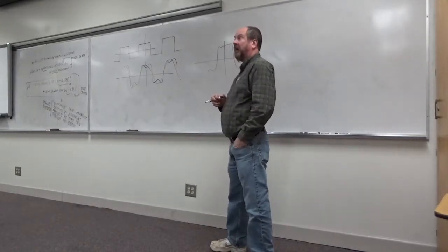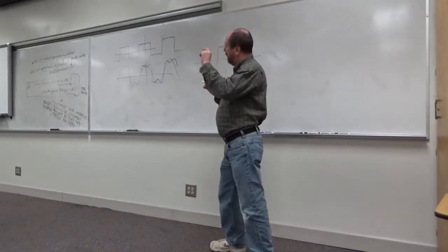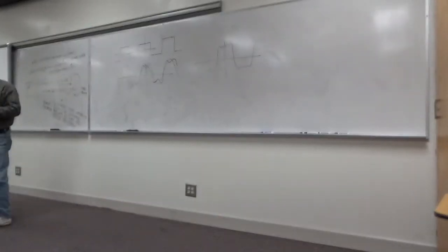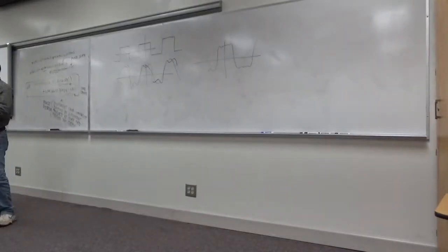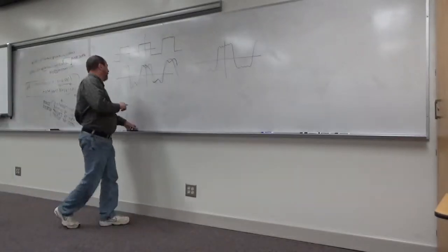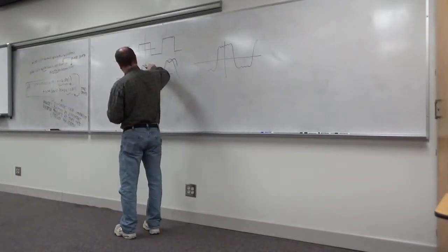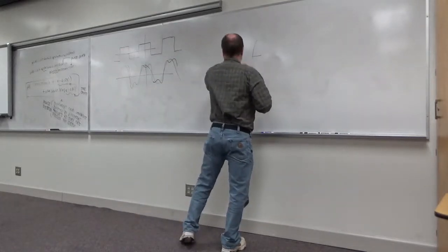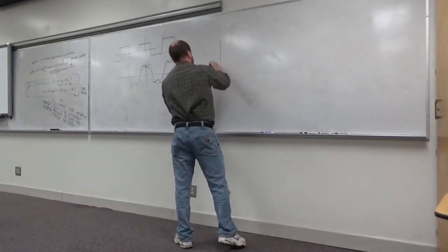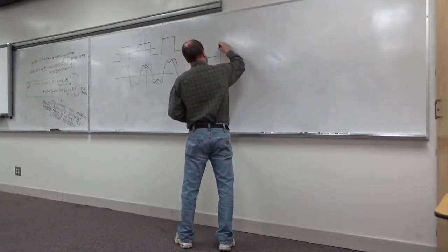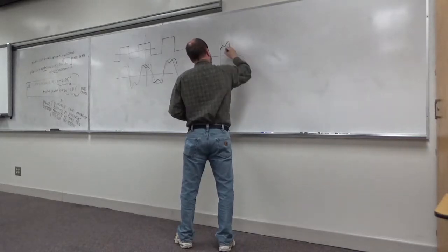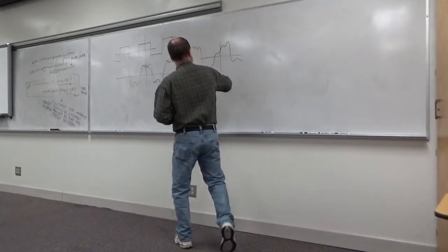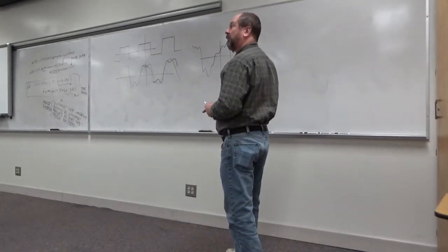And they add up. The harmonics add up in a certain way. You've got to have exactly the right coefficients out front, but you also have to have the right phase relationship. If you miss the phase relationship, notice here's the 1st harmonic, here's the 1st and 3rd harmonic. If you miss the phase relationship, you'll wind up with something like this. You'll get a signal like that. Okay? They didn't add up the way they're supposed to.